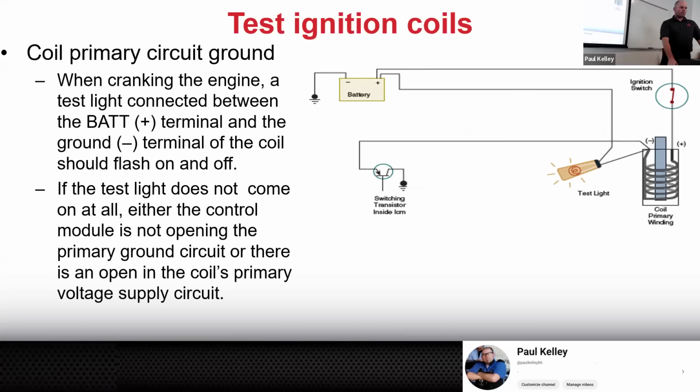If we look at this coil, here's your diagram. All right, we've got 12 volts coming off the battery, or source voltage, goes to the ignition switch. You've all heard it. We talked about this. When you hear the term "turn on the ignition," what that literally means is turn the key. But what it actually means is turn the key so that you close the switch so that your ignition coil gets voltage. Do you know that's what that meant?